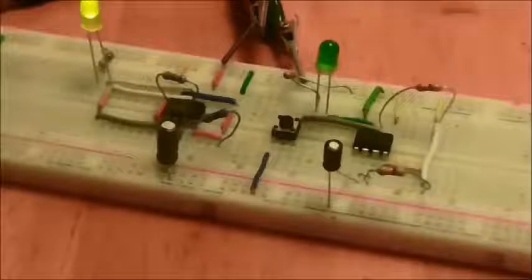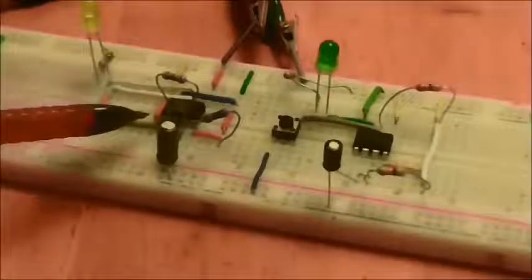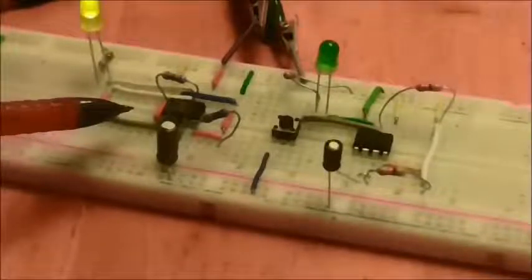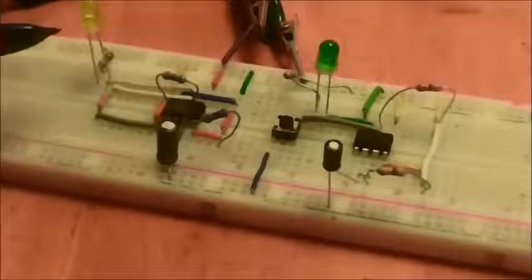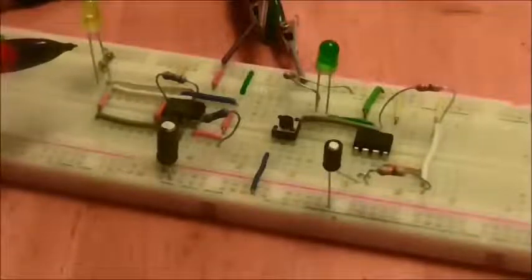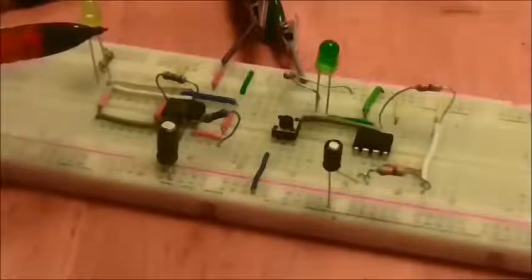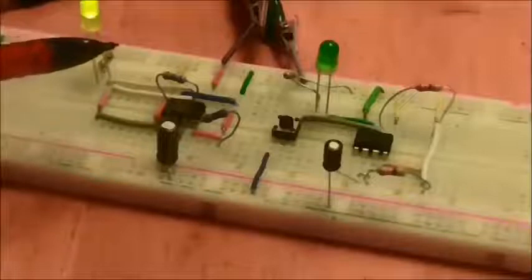Now in the pamphlets that accompany this film you will find these worked as practical examples, but while we've got the components spread out on the breadboard in front of us, what we might as well do is saunter through and have a look at the maths in a practical fashion. So we'll start with the astable, and for the astable we need to know two things. We need to know T1, which is the time it's on, T2, which is the time it's off. And to get T1 we say 0.693 multiplied by R1 plus R2 multiplied by C1.